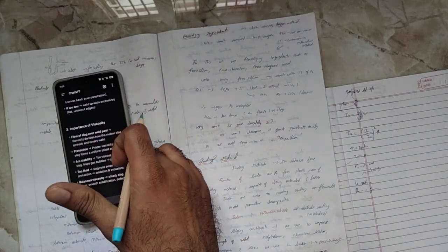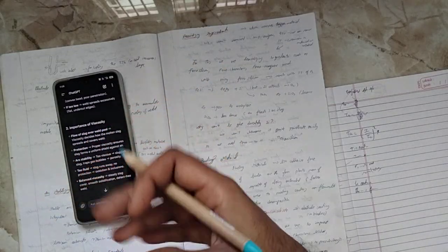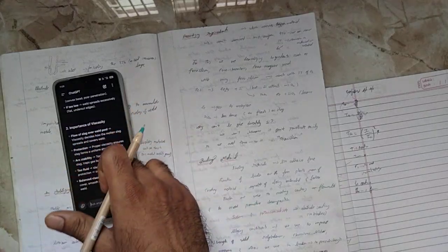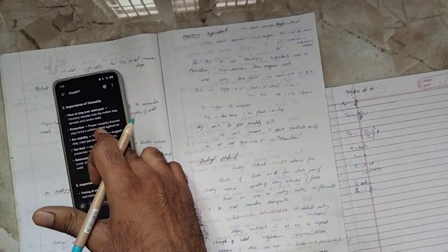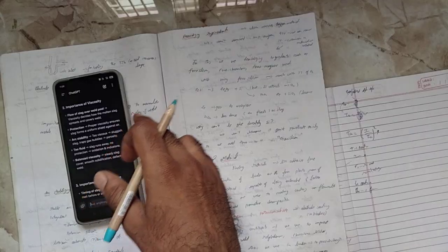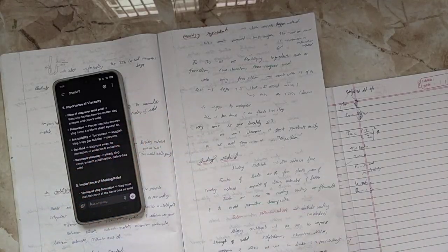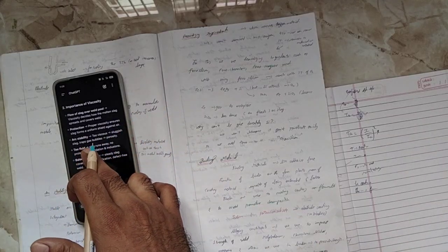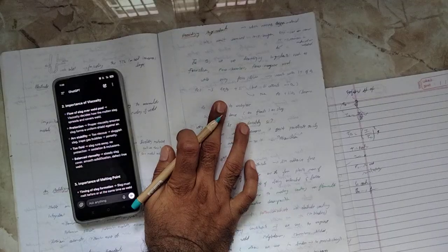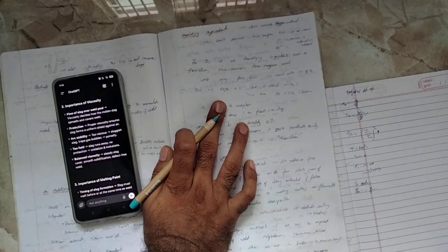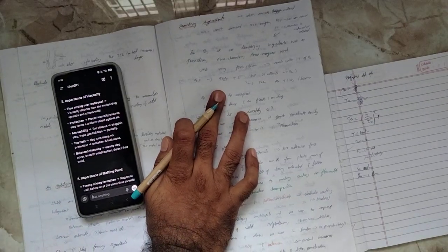So okay, why is viscosity important? Because viscosity tells how well the slag will cover everything. Proper viscosity ensures the slag covers the weld and provides protection against air. The next thing you can see is stability. Too viscous, sludgy slag traps gas bubbles, and that also leads to porosity. So that's why each and everything is important.